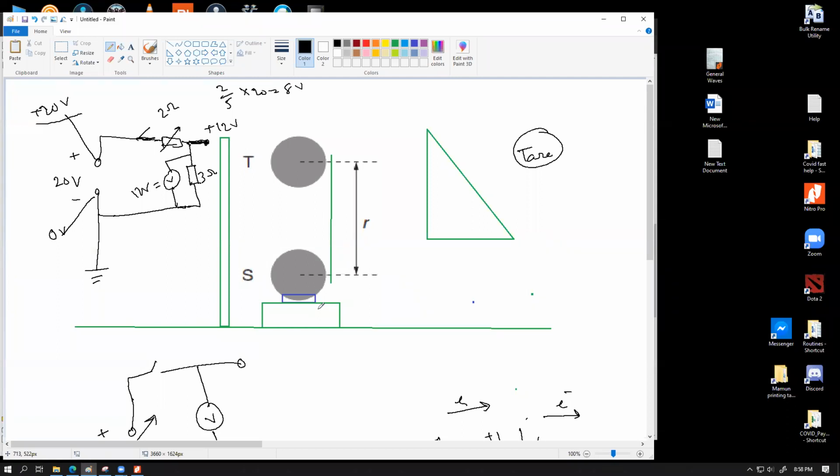Either you have to mention the scale setting of the top end balance, or you have to mention that whatever the mass value that the top end balance gives us, you have to convert that into force by W equals m into g, where g equals 10 meter per second square. You have to mention that so that we can have a proper measurement of the F value, because we are trying to find out the relation between force and the voltage. Voltage can be measured out of the voltmeter that I just showed, and the force has to be defined in a practical, achievable way so that you can have a proper way to measure that as well. So that's what that comes in.